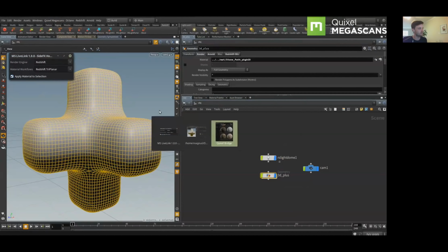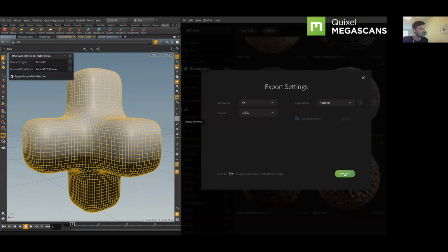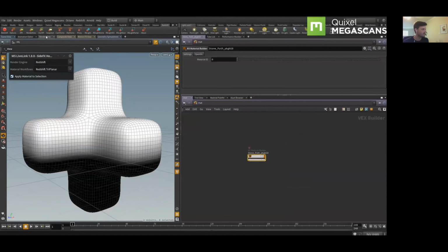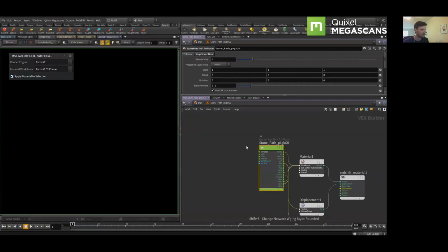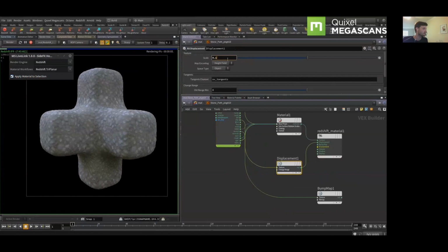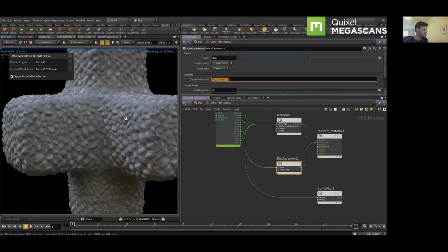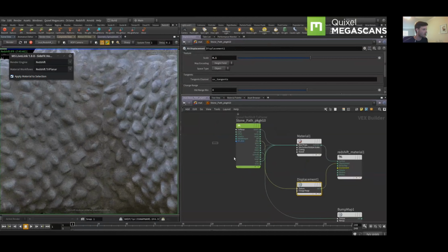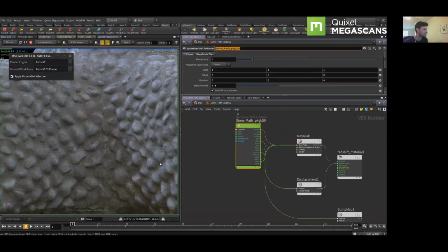And in this example, we're going to be using the triplanar setup and looking at how that works. So within just a few clicks, you have your material fully set up. We launched the IPR, you can see how that's looking. We just need to tweak the displacement a little bit to kind of suit what you're going for, but for the most part, it's all there.